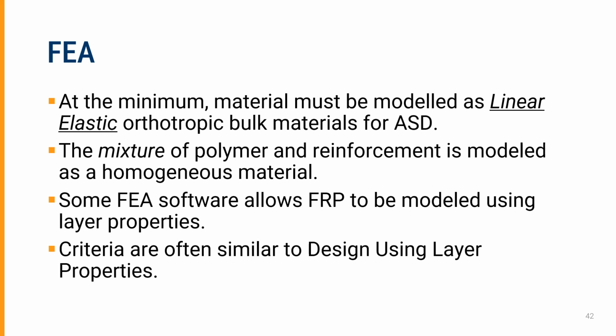Finite element analysis can be a little bit of a challenge with FRP. The reason is that at the minimum, the material must be modeled as linear, elastic, orthotropic bulk materials. The mixture of the polymer and the reinforcement is modeled as a homogeneous material. Now, some FEA software allows FRP to be modeled using layer properties.